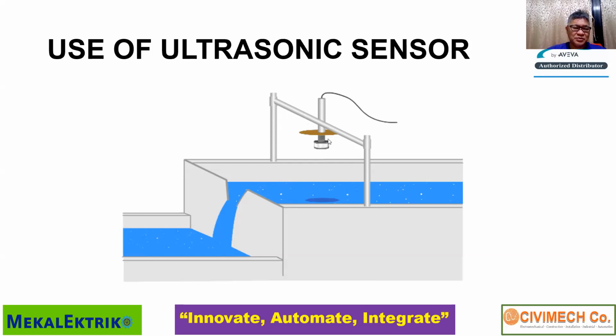So there are a lot of ways to measure the flow rate. First is you measure the depth and do the calculation. Also, you can measure the velocity, also using an ultrasonic sensor. There's no direct measurement of flow rate. The only way to measure flow rate is measuring velocity or measuring pressure difference or head.